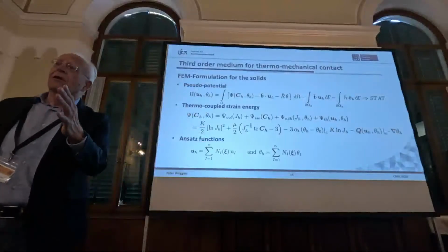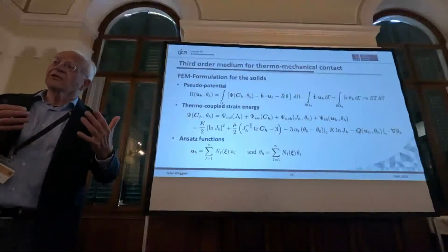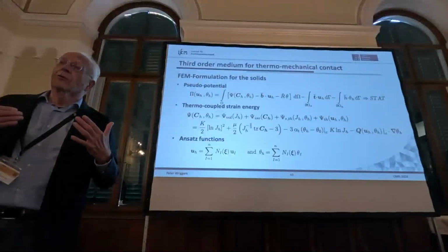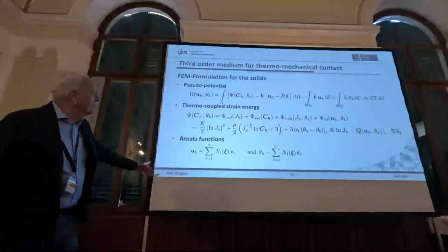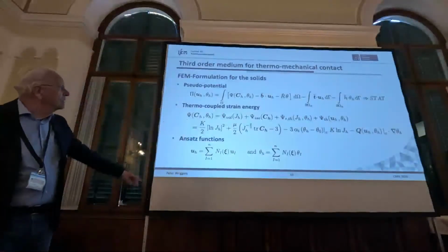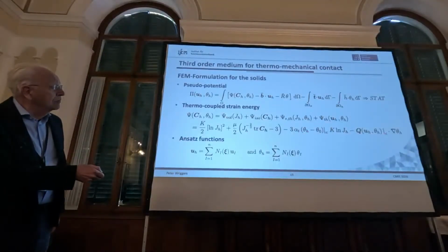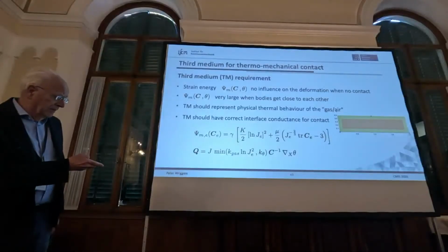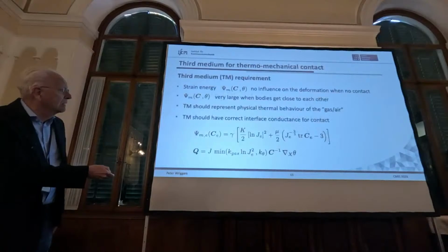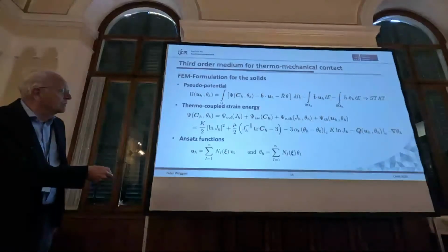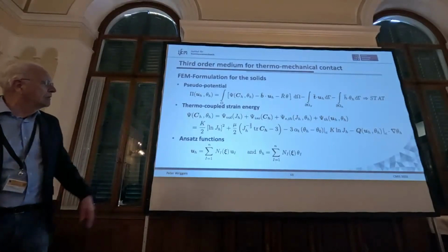The old way, what we did for large strain, going to the current configuration, actually produces the slowest code with automatic differentiation. But it was easier to code for us in the old days. Anyway, this is what we use, and you take the strain energy, and then you have to fix some variables when you do the differentiation, which I have shown here. In this case the thermal parts have to be fixed during the iteration, the first derivative, and then everything is fine.